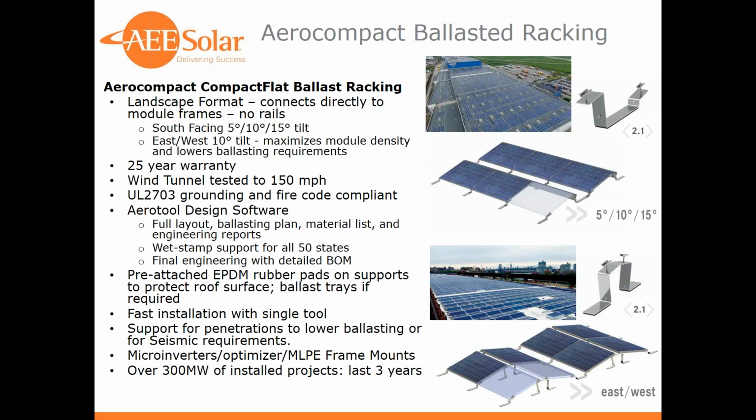Here is an example of the ballasted racking that we offer, and it is the best seller so far at AEE Solar. AeroCompact has been really great working with us. They have stock in the US and ship fairly quickly. They have a south-facing 5, 10, and 15 degree tilt array, an east-facing 10 degree tilt, and an east-west 10 degree tilt, and that 10 degree east-west really maximizes the module density and generally lowers the ballasting requirements.